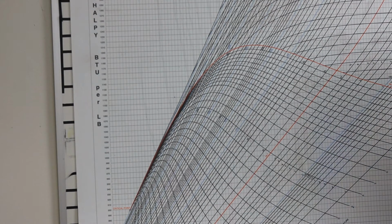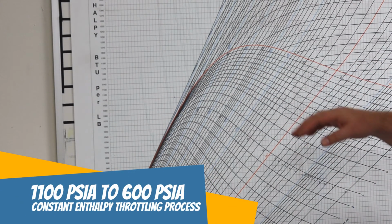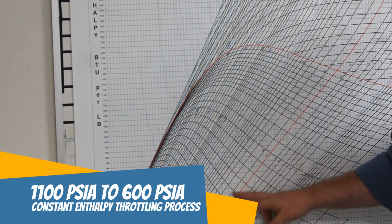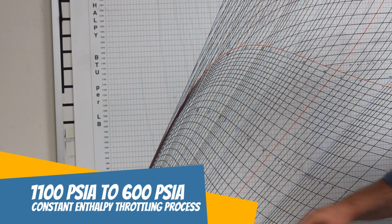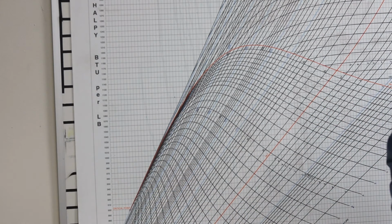So again, understanding what the process is half of the question. And if I'm asking you a throttling process, I'm asking you specifically something different than a turbine process, right? A turbine process, like we worked through, was an isentropic process. It goes vertically on your Mollier diagram, constant entropy. A throttling process, where steam goes through a steam valve, a governor valve, through some valves into a steam chest, is a little different.